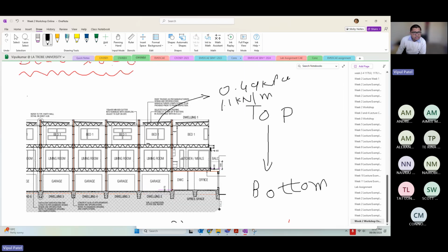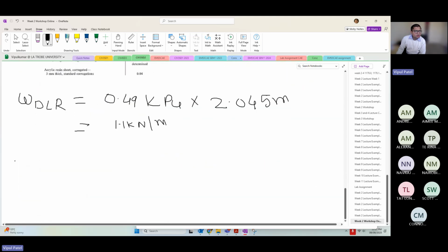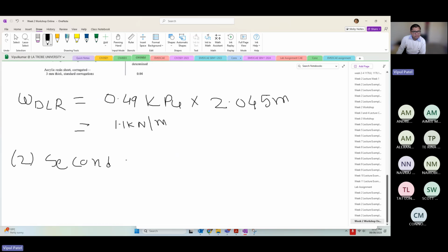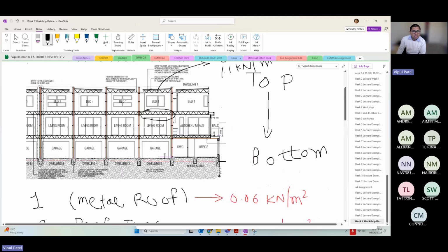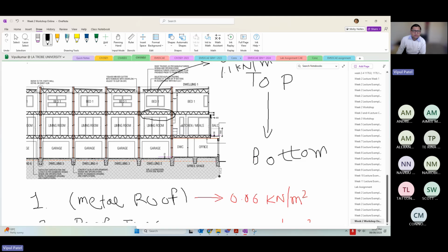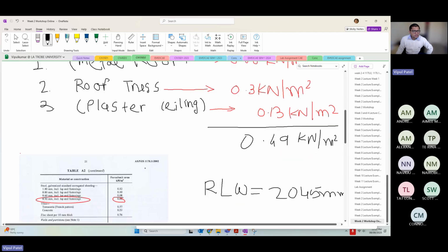Now let's talk about this second floor. So the roof is finished. Number two is we're going to do the second floor. Now the second floor is the same thing as a roof, but there is no sheeting. There will be plasterboard here. Then there is a truss here, and there is a plasterboard here. Because if there are bedrooms, then these bedrooms have this flooring. We don't have sheeting like here, but then you have floorboards or plasterboards, and then you have truss, and then you have ceilings.